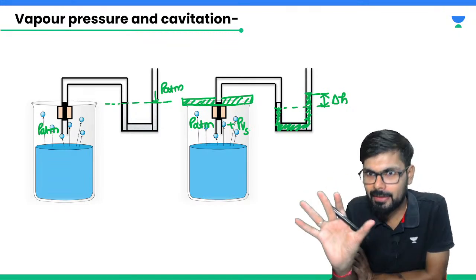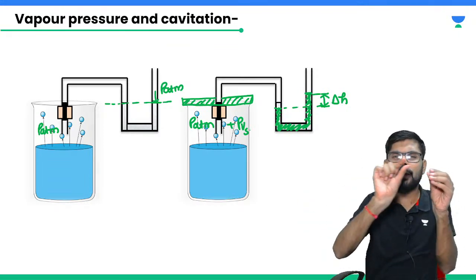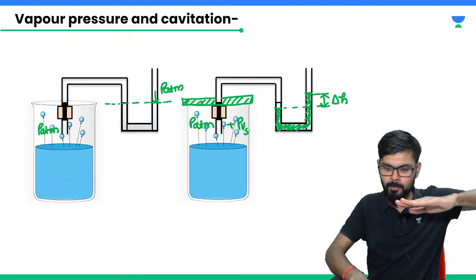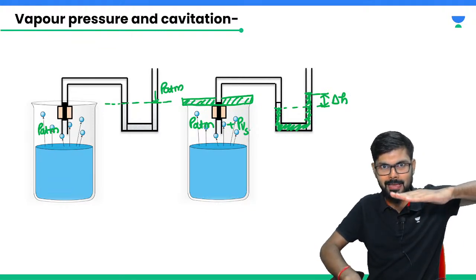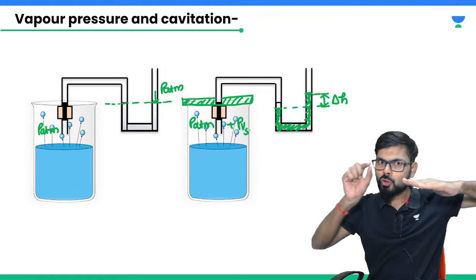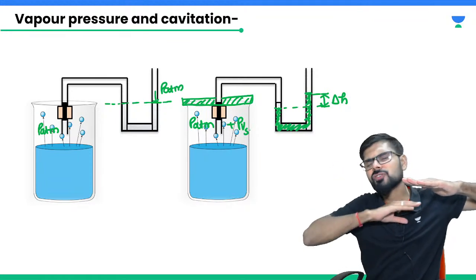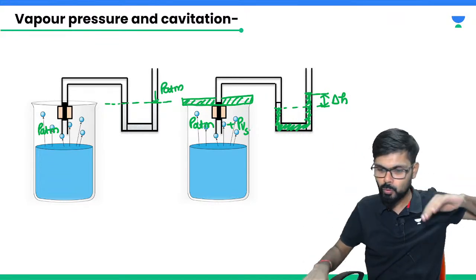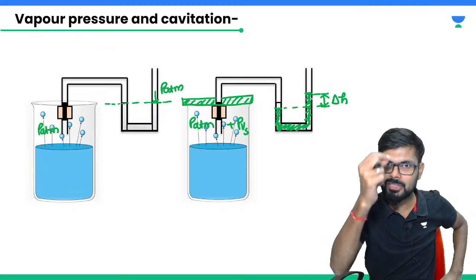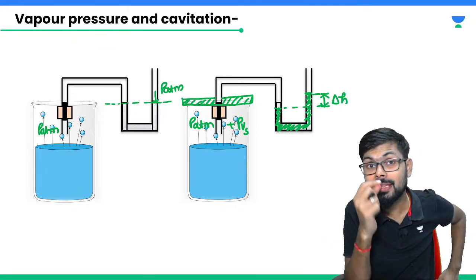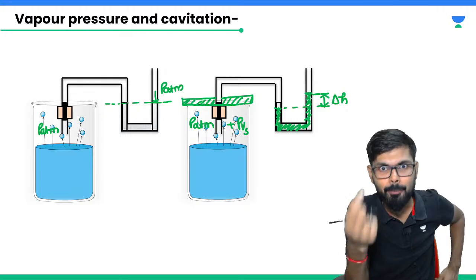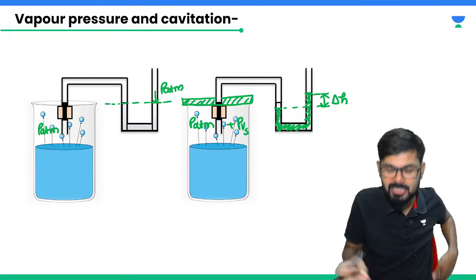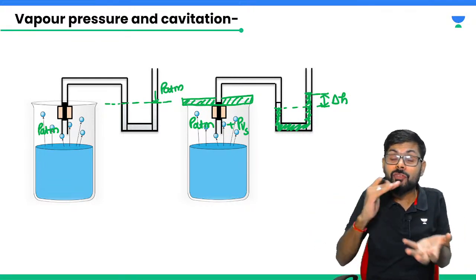Please listen here carefully. What you can do, if you have a perfectly fine U-tube manometer, then do one thing, put it into a glass where water is there and just check that. Very slow, just give some time because this phenomenon is very slow. Evaporation is a very slow phenomenon. Just give 1-2 hours. Then after 1-2 hours, you will find that there is somewhat of a deflection. Why is this deflection coming? Because of the vapor pressure, because inside the pressure will be somewhat more than atmospheric pressure, because these molecules are added, and this will keep on increasing.